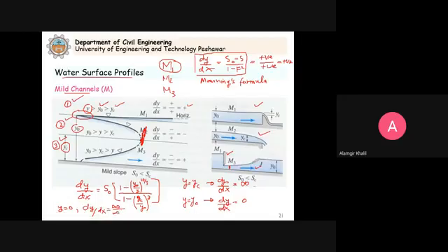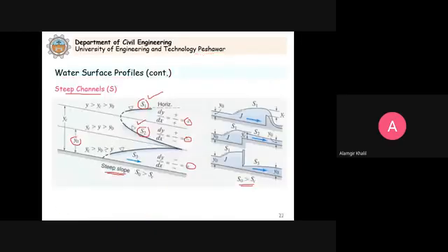We cannot show it as a straight line, because this equation coming from Manning's formula gives us the form infinity by infinity. So the gradually varied flow theory will not work here. That's why we cannot plot a profile here and it is shown dash dash. It cannot be a straight line here. Clear? So these are a few things that you should understand from this theory.